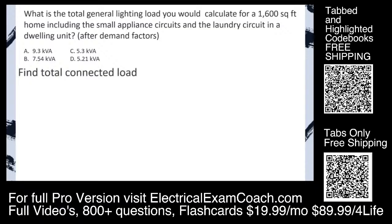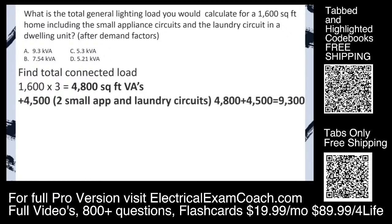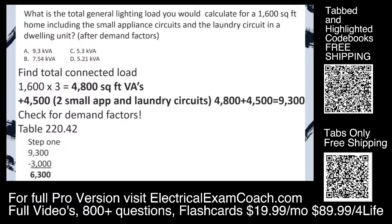Step 1, find our total connected load. We're going to take our 1,600 square foot, multiplied by 3 VAs per square foot, and that equals 4,800 general square foot VAs. Now we need to tack on our 4,500 for our 2 small appliance and 1 laundry circuits. Then we take that load and we check for demand factors. We head to table 220.42. We're going to take our first 3,000 at 100%. Then we're going to take that remainder at 35%.